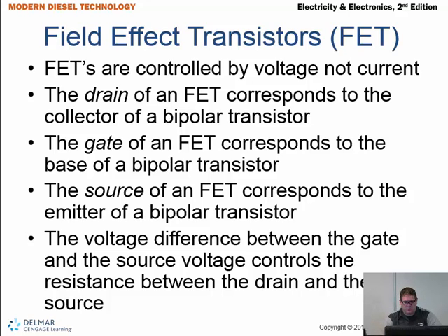The voltage difference between the gate and the source controls the resistance between the drain and the source, and so we'll talk a little bit about that going forward. But just so you understand, this is just like our relays. We are controlling an output with an input, and that's really kind of what you need to know about this at this point.